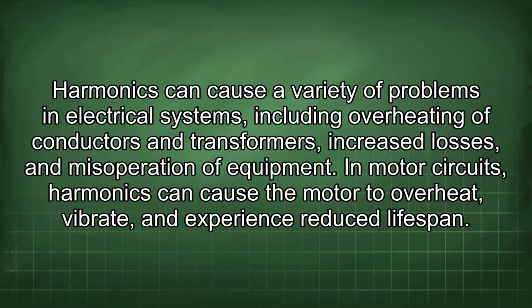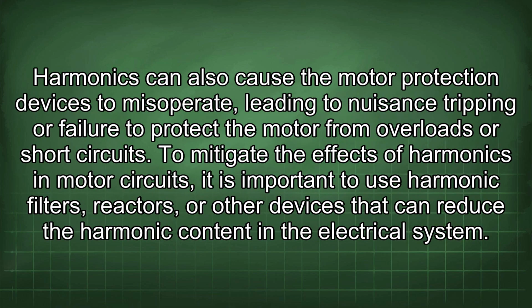Harmonics can cause a variety of problems in electrical systems, including overheating of conductors and transformers, increased losses, and misoperation of equipment. In motor circuits, harmonics can cause the motor to overheat, vibrate, and experience reduced lifespan. Harmonics can also cause the motor protection devices to misoperate, leading to nuisance tripping or failure to protect the motor from overloads or short circuits.